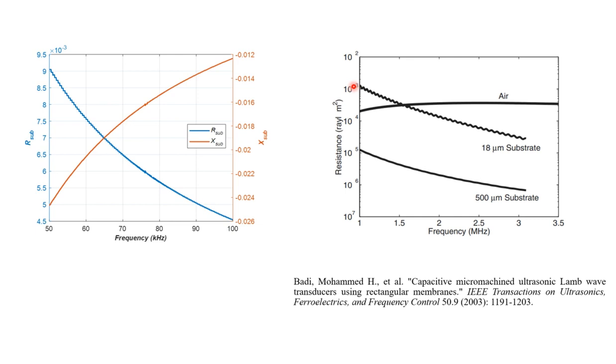for which they have characterized through laser vibrometer analysis that they have both the lower order symmetrical and anti-symmetrical Lamb wave modes, A0 and S0. A0 vanishes for very thin membranes with thin substrates, but S0 retains very stable steady state values if you remember the dispersive curves of Lamb waves, but the higher order modes are in cutoff.